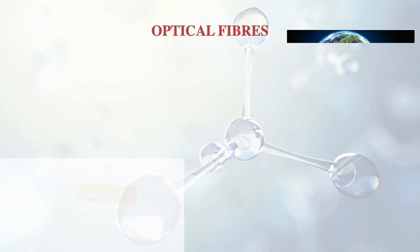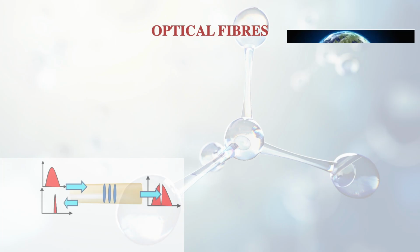An FBG is a set of gratings imprinted in a small segment of the optical fiber such that they reflect a particular wavelength of light and allow transmission of the rest. If a wide band of light is passed through the fiber, most of the components are transmitted through the fiber, but one particular wavelength, which is called the Bragg wavelength, is reflected back.